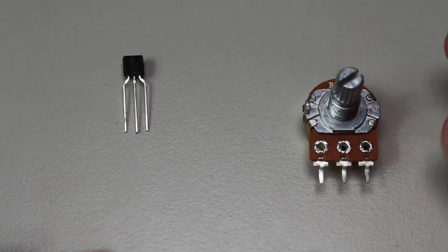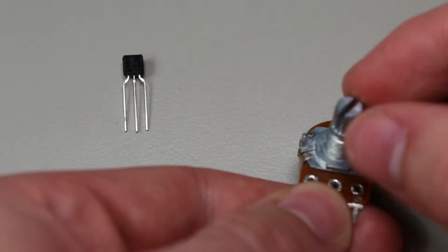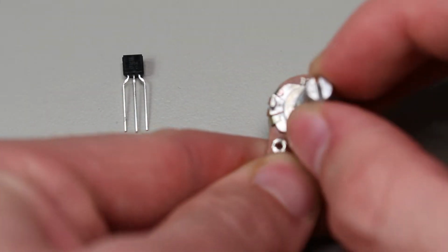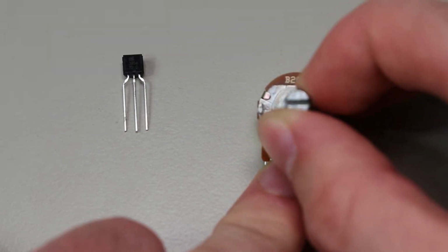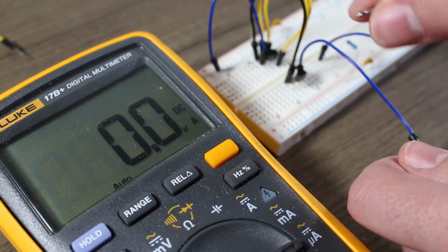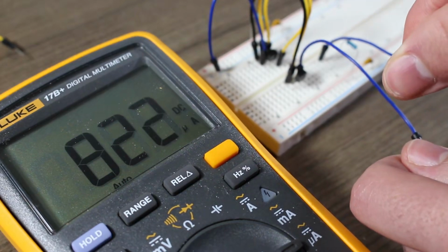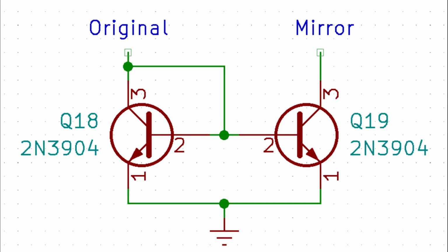Like I explained much earlier in the video, transistors are like adjustable current sources. The problem is that, by themselves, the adjustable part is hard to predict and it varies with several factors, making it rather unpredictable and unstable. However, with a few extra components, we can remove most of the uncertainty and make a much more stable current source. Let me introduce the basic current mirror. It consists of just two transistors with their bases and emitters tied together. One of the transistors will have its base and collector tied together.